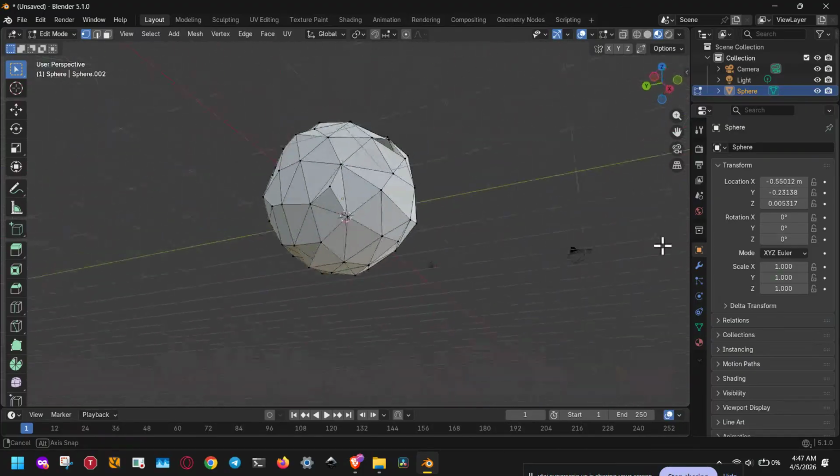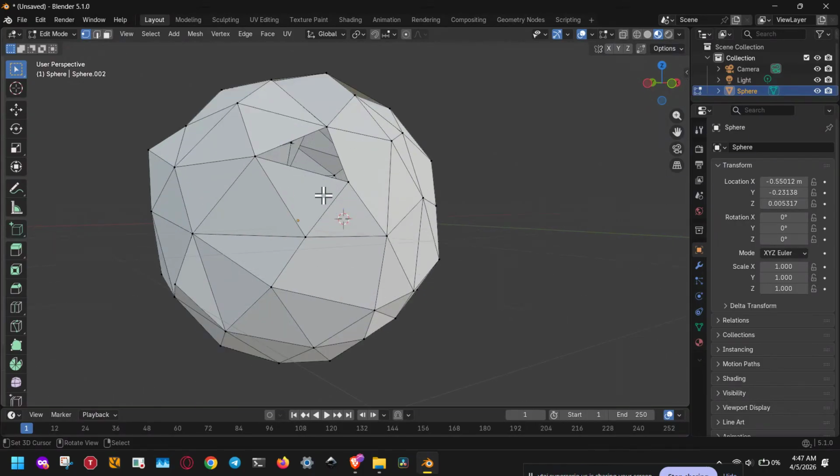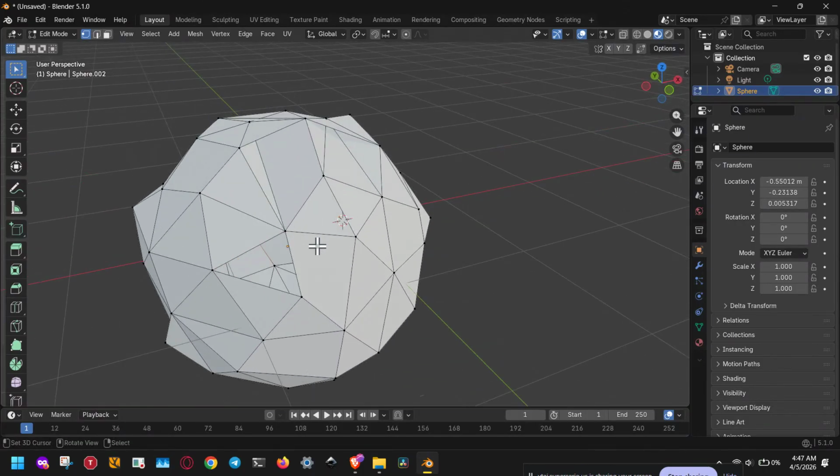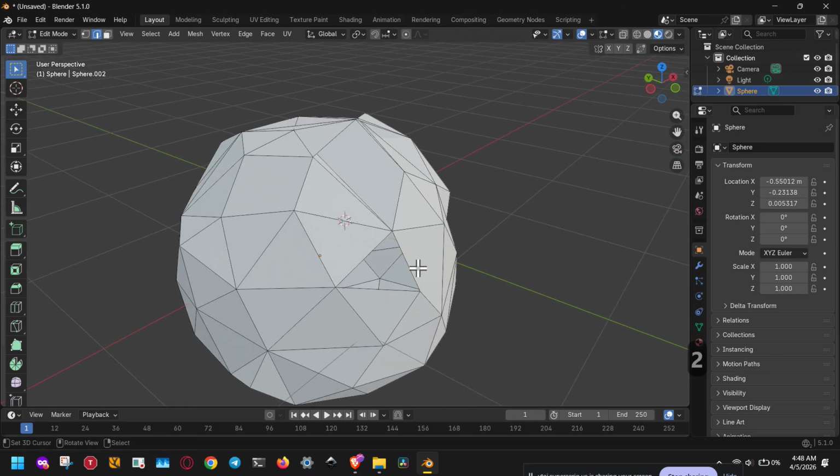At this point, take a moment to inspect your mesh, rotate around it, and look for any open areas, broken sections, or edges that need to be connected. If you find a simple hole with clear boundary edges, you can close it manually. Select the open edges around the hole, then press F. Blender will create a face and fill that opening. This is best for small, simple holes, where one face is enough to patch the gap.